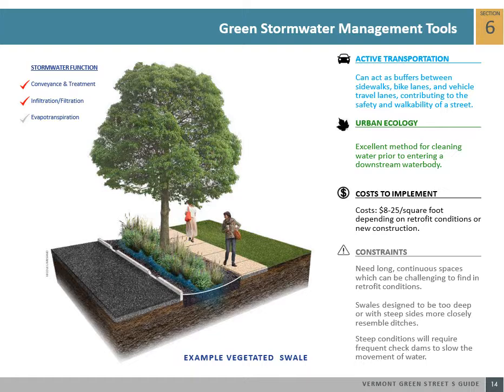Green gutters are useful along wide streetscapes as well. In many cases, simply narrowing the travel lanes along a residential or commercial street can yield enough space for green gutter installation. Similarly, for small parking lots, shortening parking stall lengths can provide space at the front of parked cars for a narrow green gutter application around the perimeter of the lot.